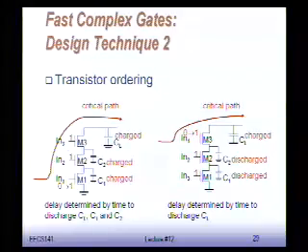So when the gate operates, you know that in 1, in 2, and in 3 are never going to arrive at the same time. But there's always one of them that is going to arrive first, right? So then what you want to avoid doing is putting the guy that arrives last at the bottom, because we already derived before that this transition is the slowest. What you want to do instead is put the guy that arrives last closest to the output. Because in this case, C2 and C1 are already discharged, and this transition is the fastest. In this way, the overall transition speed is maximized, right?